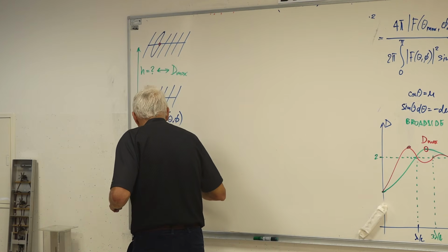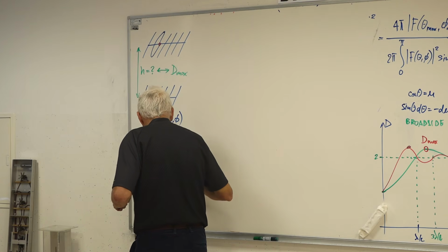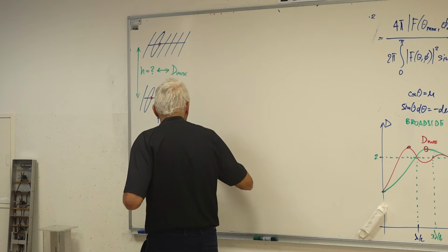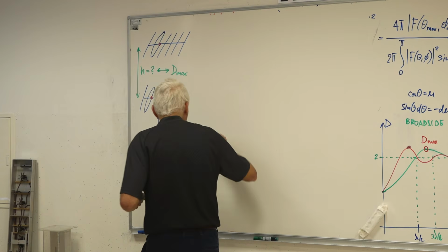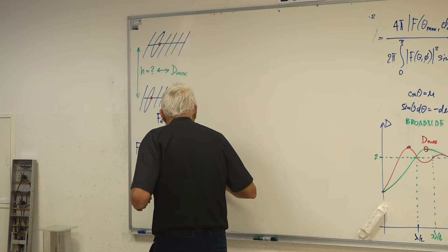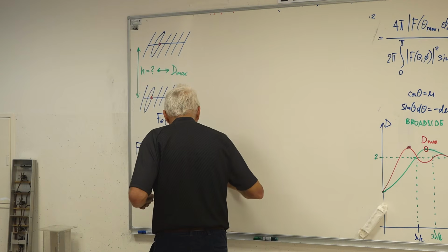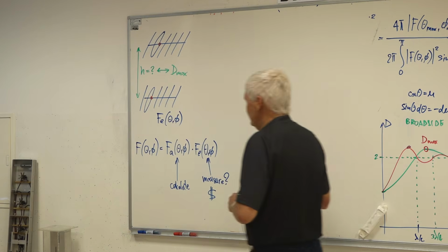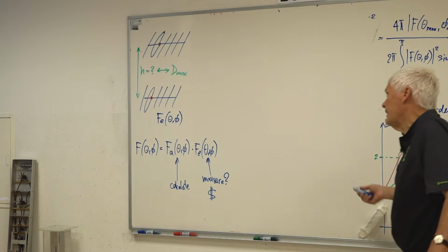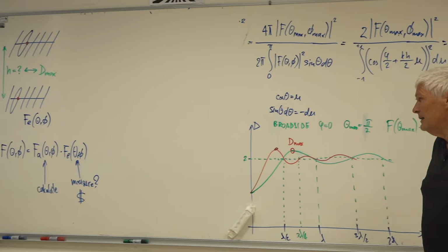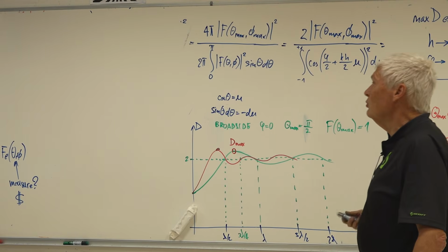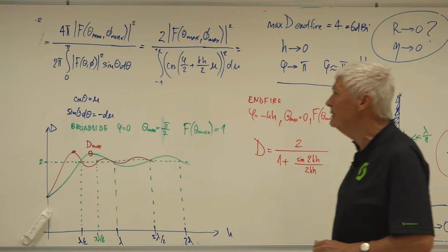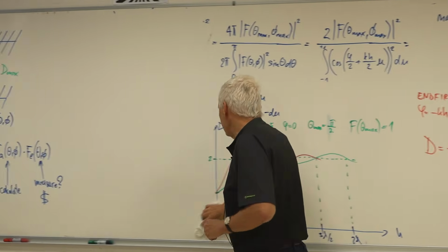But the element radiation pattern, f of theta and phi, I can only measure, and the measurement is expensive. It's a commercial antenna. I cannot modify it. It's just an item I bought in the store. So how to find the optimum spacing between these two antennas?